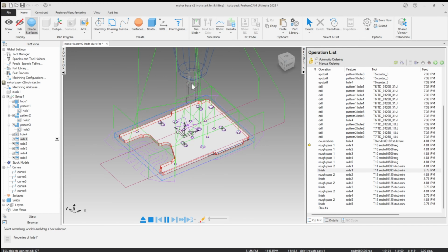And here we can see we're cutting the perimeter, and it was a 1/2-inch tool. And now we're using a smaller one, and that was picking out those corners. That was the 093 tool that I said you can go down to. And so it's getting the tighter areas, tighter radii. Okay, so we work down the list, we keep going,